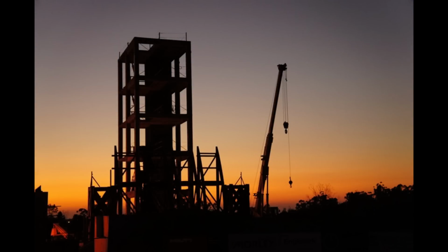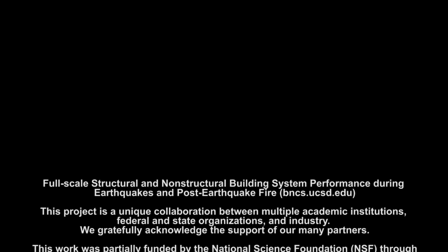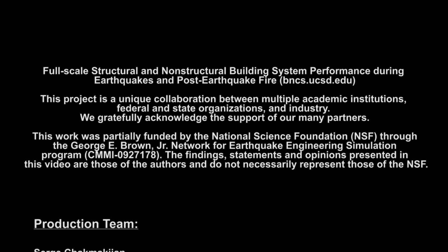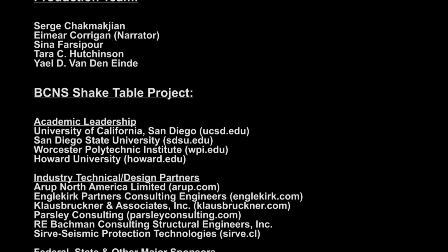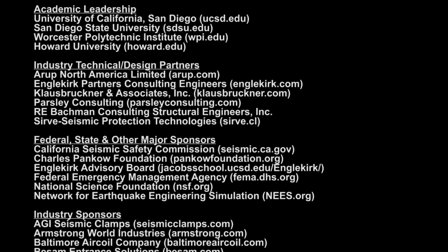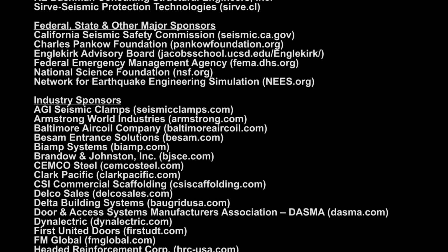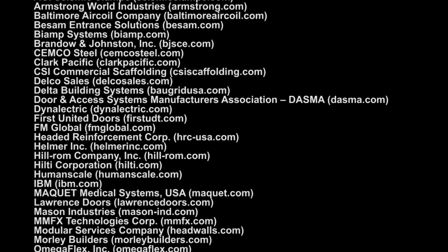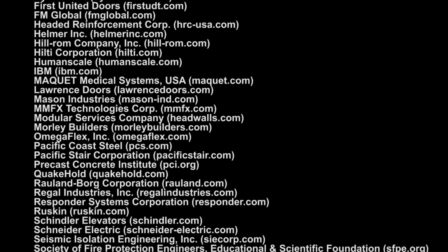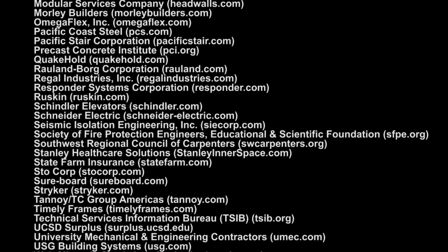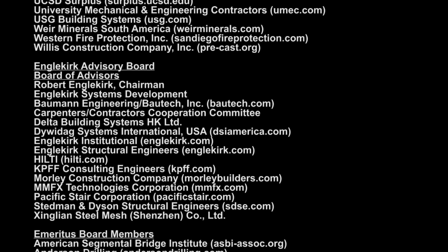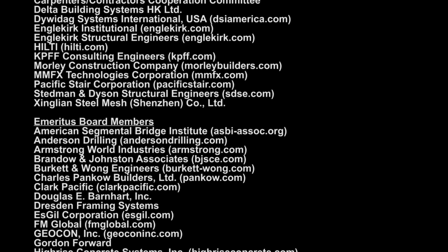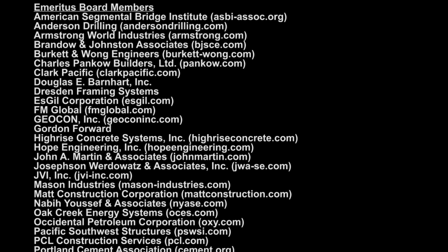This video utilised a 5-storey building test at UCSD as a case study to learn the basic phases of construction for a cast-in-place foundation of a tall building. The conventional preparation and installation of rebar and high-strength post-tensioning tendons were discussed, as well as basic requirements for falsework, system formwork and safety scaffolding. Additionally, standard methods to pour concrete into the foundation were highlighted, including the different tests that are conducted during and after the pouring of the concrete. Because this experiment was conducted on a shake table, some differences from the conventional foundation construction practices, such as the use of base isolators and the need for formwork, were demonstrated in the video.